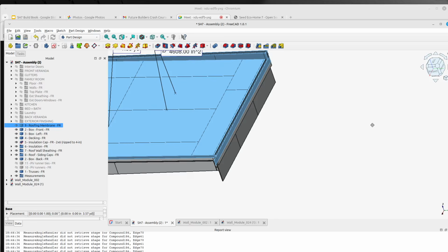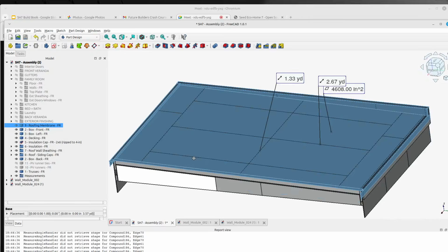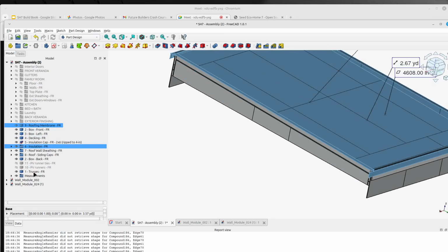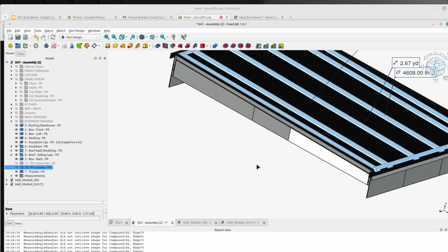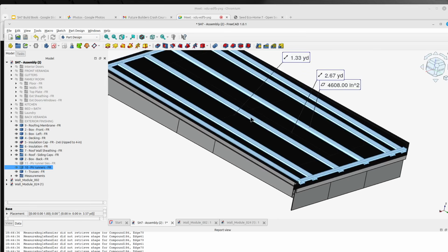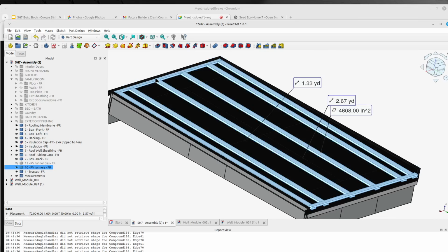So there's a continuous roof membrane, that's the water barrier. So it's a membrane roof, followed by the runners for the photovoltaics. So this is to which we mount the photovoltaics. No penetrations through that. There's metal connectors connecting to the side of the house.